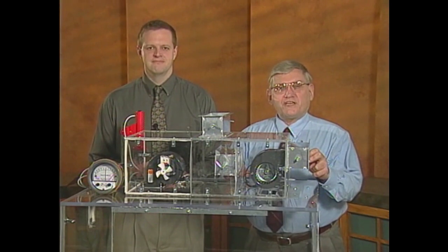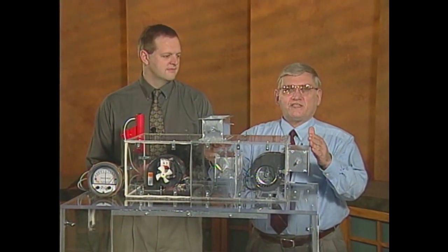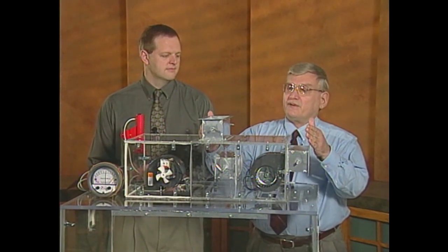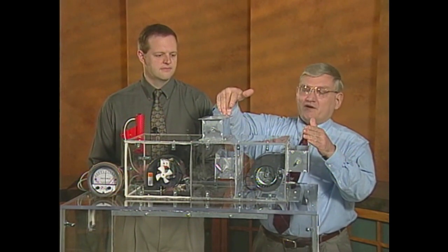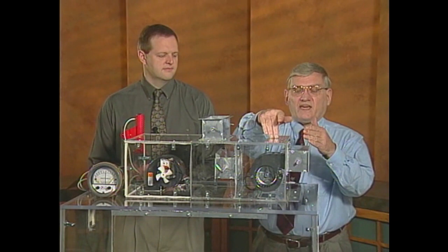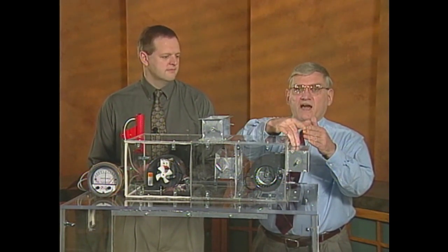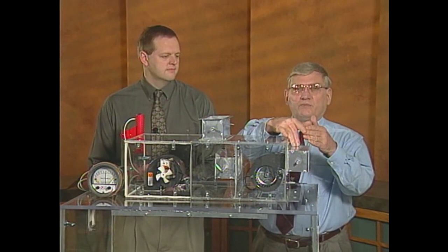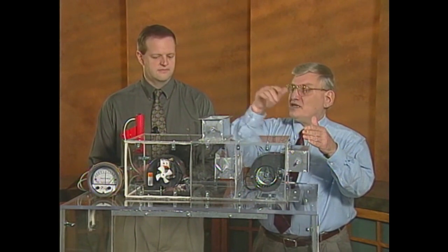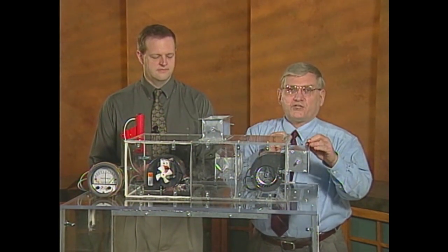Using the building pressurization model again, we've replaced the mixing box with a module that includes a central on-off relief fan. That's this section of the model right here. Briefly, it has an outside air damper, a return air damper, a central relief fan, and a central relief damper. And we'll be using these two in an on-off configuration to help control building pressure. Notice the central relief fan is in parallel with the supply fan in terms of a unit configuration.